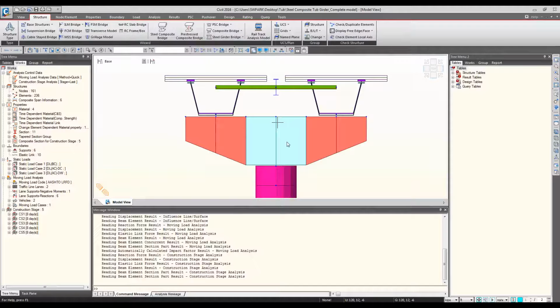So that's why I recommend that, for the rough design, like a primary model, you first create this model through the widget. And if you want to put in a more complex bracing system, let's say inverted K brace or top flange lateral bracing, you can do some modification inside of the section in steel top sections. But as I mentioned before, those are single beams.